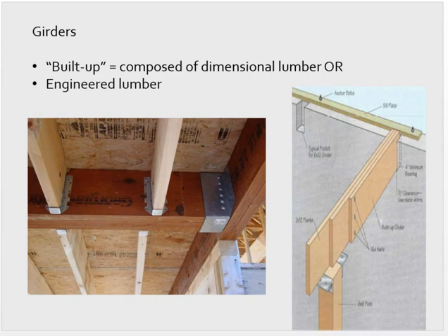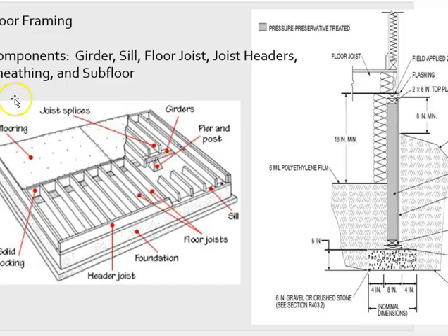Okay, moving on. So here are some views of a girder. Here we have an engineered girder, engineered lumber, a laminate or something. I can't exactly tell by looking at this particular image. So it's coming over, and then it's anchored and ledged with this beam as well. And these joists are mounted flush with the top of the girder. And so that was in contrast to what we saw over here, where we see the joists running over the